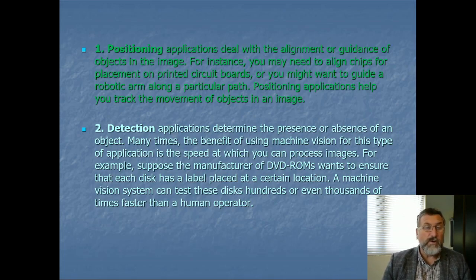And if you don't get this in the right order, this broaching operation, or if you don't do it, then it causes a problem with the synchronizer hub, which can cause a problem in the automatic gearbox of the pickup truck. And of course, if you have to take the gearbox apart to replace that, you're talking about thousands of dollars of work for a part which is just a couple of dollars in value. So it's very critical. And again, it's a fairly boring sort of task, which humans are not particularly good at, but machine vision is particularly good for checking the presence of marks on the hub in that case to show that the broaching operation had been done.